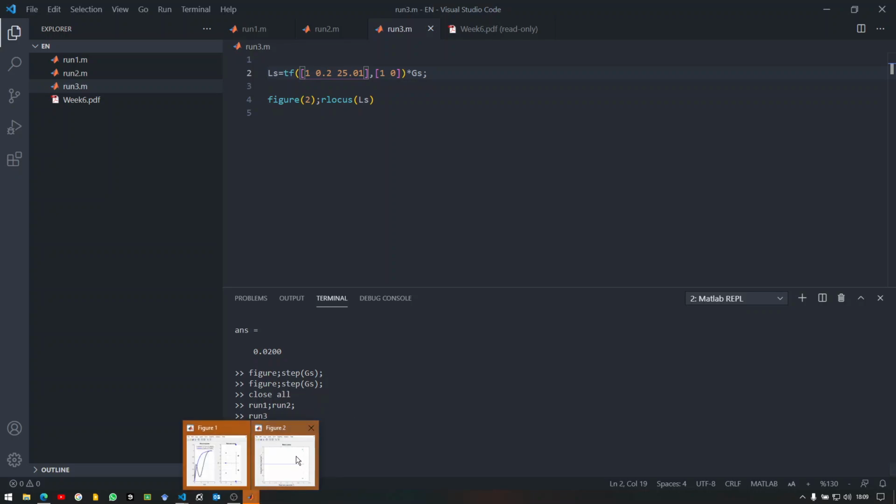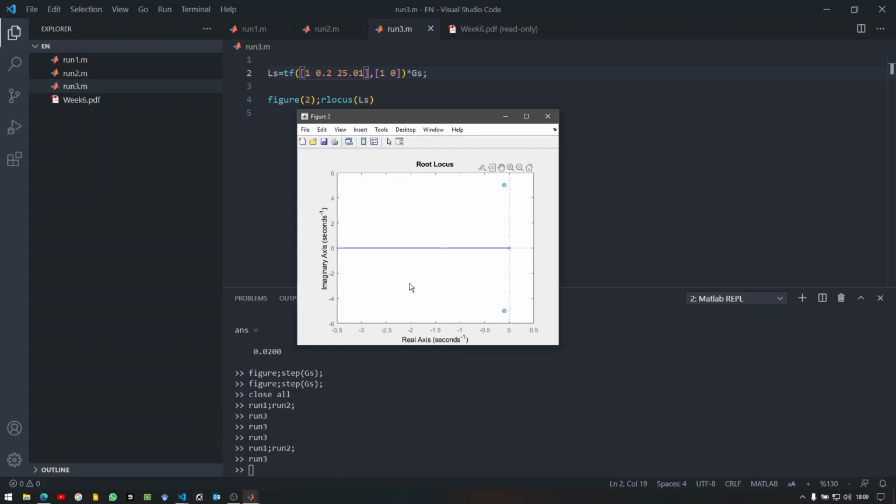I can see that I'm cancelling out the poles and zeros. If I would add a pole, let's say at -4, then this root locus would pass through -2 here, because they would meet each other at exactly the middle of this line.